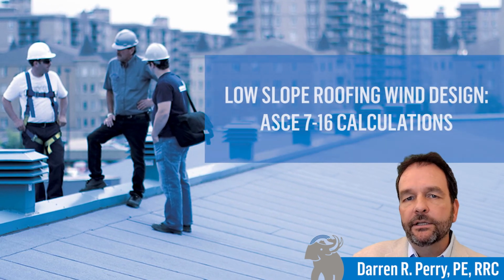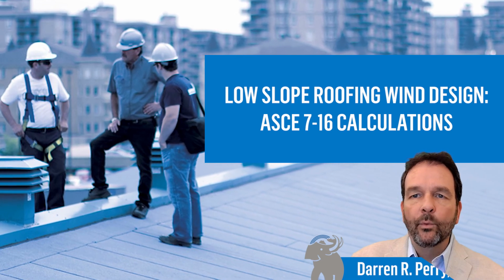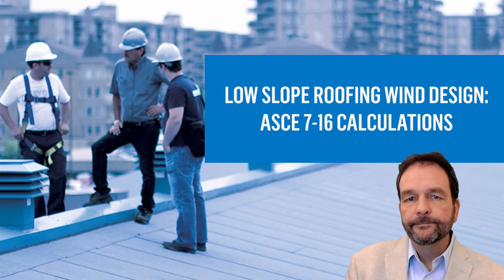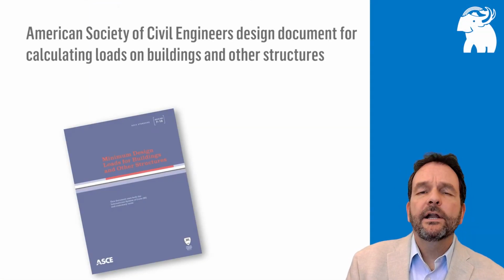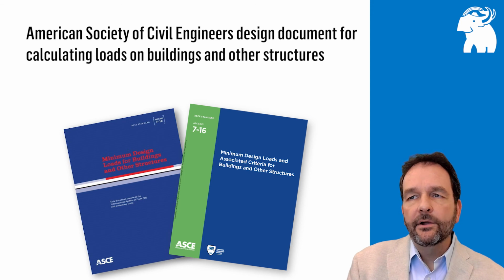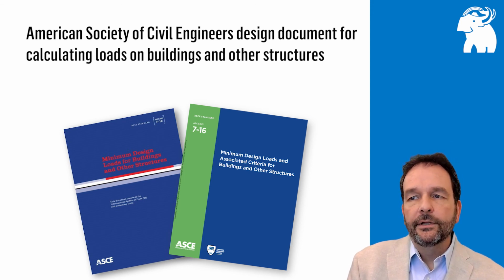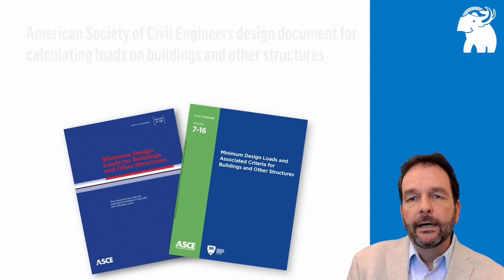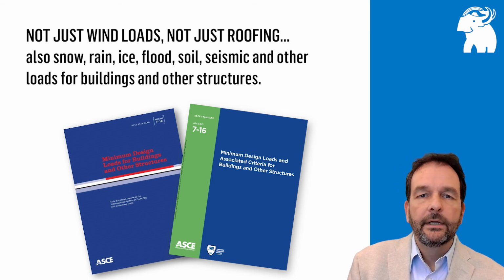And today our objective is to review ASCE 7-16 and the methods to determine wind design pressures for low slope roofing. So what is ASCE 7? It's the American Society of Civil Engineers design document for calculating loads on buildings and other structures. It's used to calculate design wind pressures, but it's not just for wind loads, and it's not just for roofing. ASCE 7 also is used to calculate other environmental loads such as snow, rain, ice, and seismic loads for buildings and other structures.